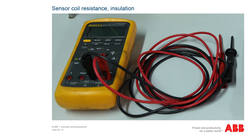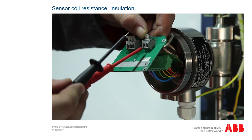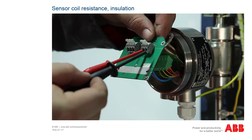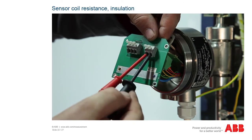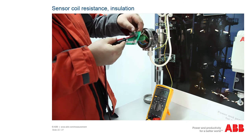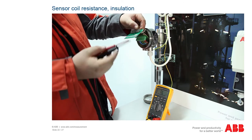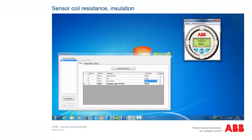First, measure the resistance of the coil. To do this, you need a resistance measuring device. Measure the coil resistance on the right-hand smaller terminal between the M1 and M2 contacts and enter the measured value in the measuring log. You can check whether the measured value is correct by looking at the defined reference value for the coil resistance of the default fingerprint. To do this, in the menu call up the diagnosis function, then fingerprint, and then default fingerprint. All of the values of the default fingerprint are stored here.